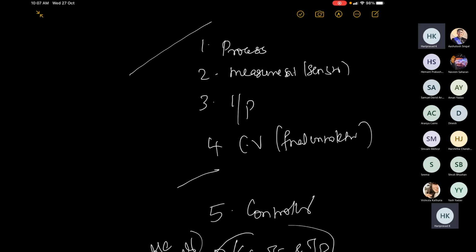If you want a hard controller, you can buy it from the market in bulk orders. If you need a soft controller, you would order a DCS system. Companies like Yokogawa, ABB, Honeywell would give you the DCS system. Their DCS system is also dumb. You would have to install everything. You will have to say this is the process, and fit in all the process schematic, everything inside.